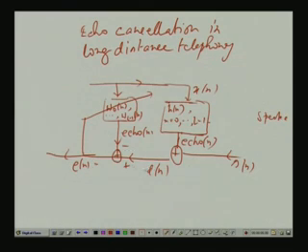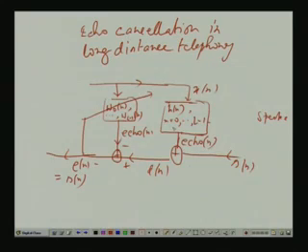So, if you take echo(n) and subtract it from d(n), you once again get back e(n) equal to s(n). So the s(n) that goes out has no echo or very little echo; this is called echo cancellation. This echo cancellation is particularly useful for data modems, because human beings can still, using their intelligence, differentiate between echo and actual sound to be heard, but if it is a data modem, a computer cannot. So, echo cancellation for data modems is very essential.